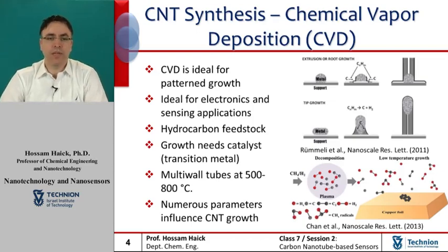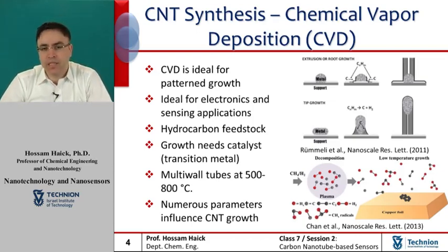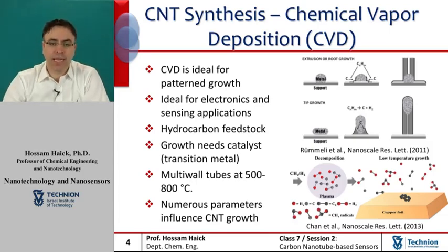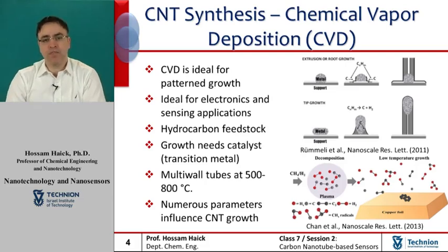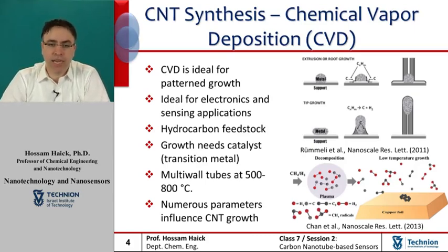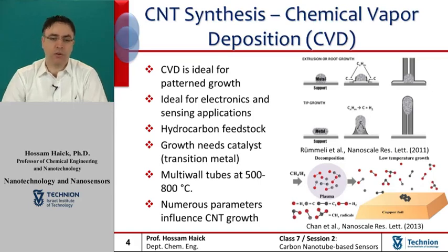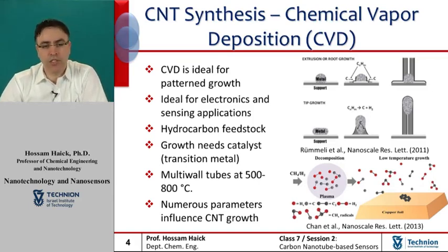The second system is tip growth. A mechanism has been postulated to account for the growth of filamentous carbon produced from metal catalyst decomposition of the acetylene. This mechanism involves the diffusion of carbon throughout the catalyst particle from the hotter leading phase, on which exothermic decomposition of the hydrocarbon occurs, to the cooler trailing phases at which the carbon is decomposed and deposited from the solution.